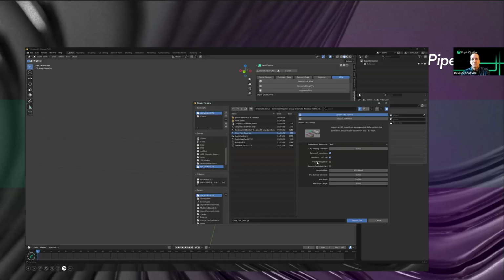You can also fix things that are inverted, for example, faces that are facing the wrong way because they were negatively scaled in the CAD app or however it was. You get inside out surfaces really easily and that kind of fixes it. And then remove occluded parts will automatically remove things that are inside the model that are invisible surfaces. You can do this on import, or you can do it later as an action. We have actions here for basically handling that.